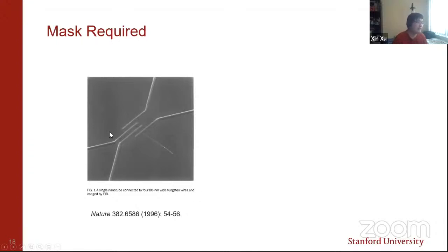And in the halo image, even from this not very high quality image, you can see some halo contamination on the carbon tube. Until now, it's weird that people underestimate the halo effect. I still see some in high impact journals that directly deposit platinum or tungsten electrodes when the samples or nanowires also experience the deposition without any protection or mask.